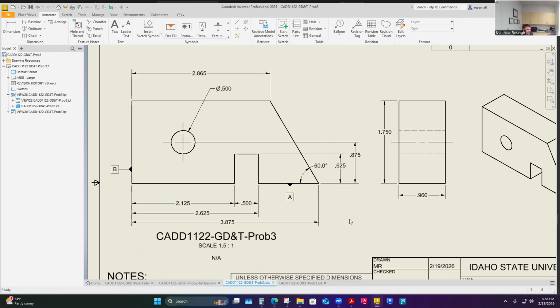Okay. So yeah, before I jump to the features of size and start doing some GD&T for those, well, we need to control one of our surfaces here. This next surface here, the right side surface. So it wants us to control it with an angularity from datum A, and let me see what the tolerance of that was.